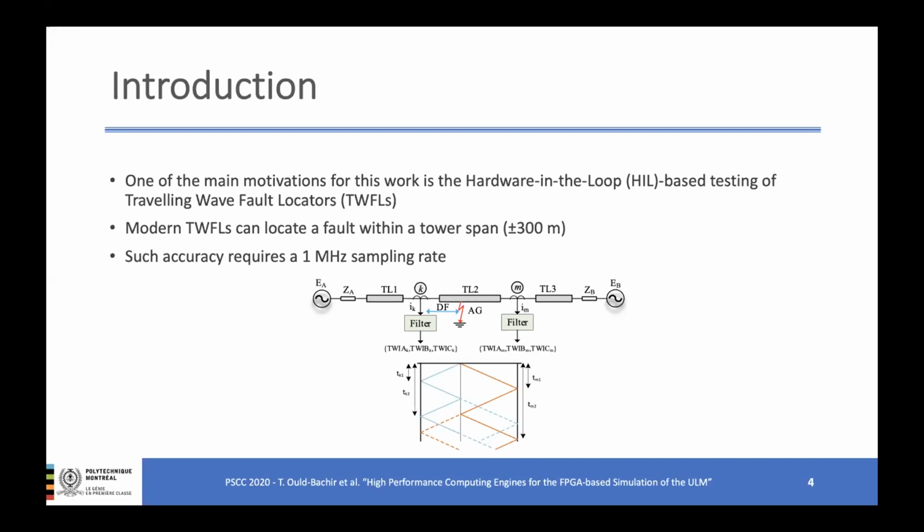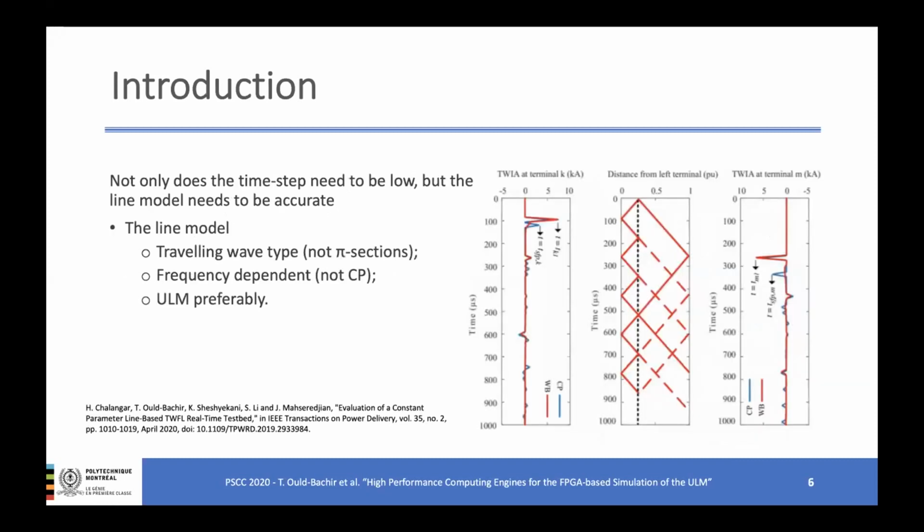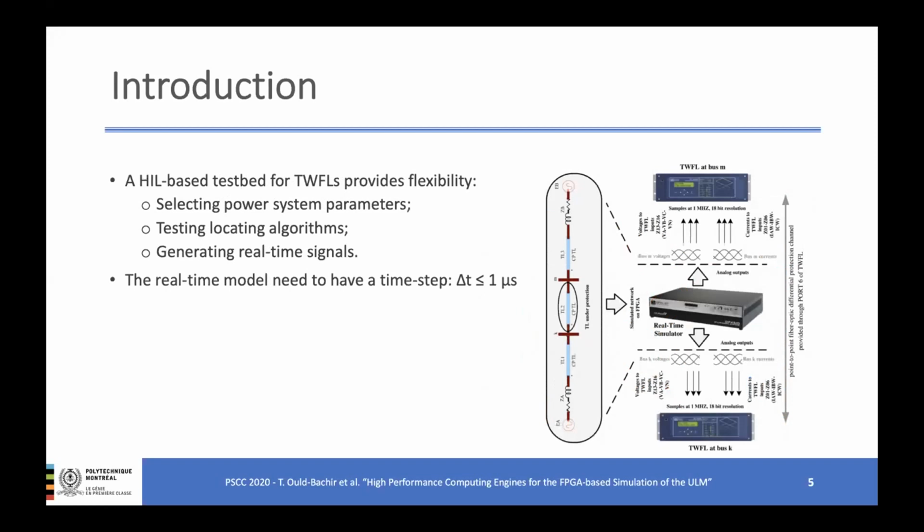And when time comes to test this kind of apparatus, there is no technology available. So there is an effort presently in real-time simulation to offer a real-time model for these relays. Here we see the relays from SEL, and this figure comes from another paper we published with the co-authors. The purpose here is to emulate the simple grid on the simulator and feed the relays with real signals and test the algorithm. So it allows a lot of flexibility in testing their algorithm and scenarios.